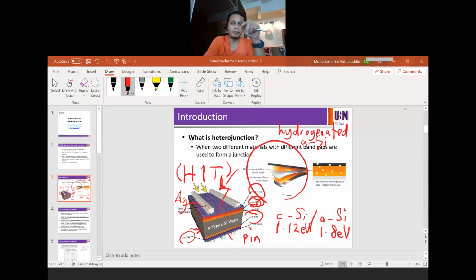But if the TCO conductivity is not enough, or the TCO layer is not in the optimal condition, you may need to also use metal contact to better extract the carriers. So in this case, that's why they use both types of contact, metal and non-metal, to be able to extract the carriers from the device.